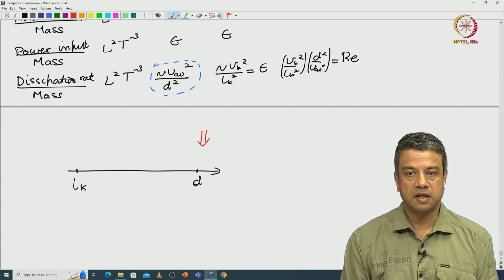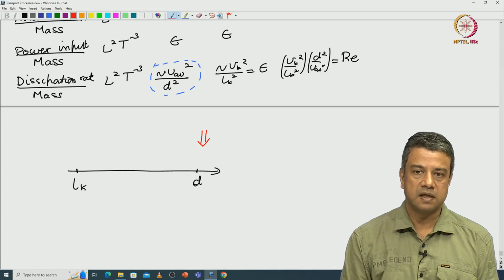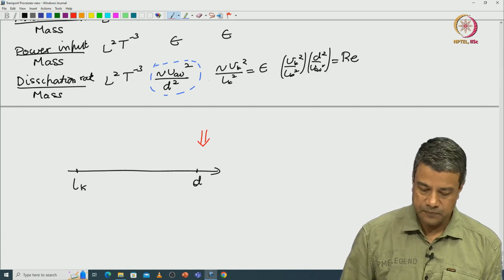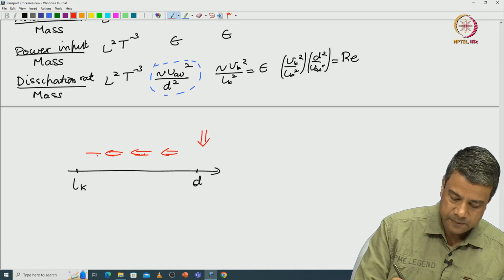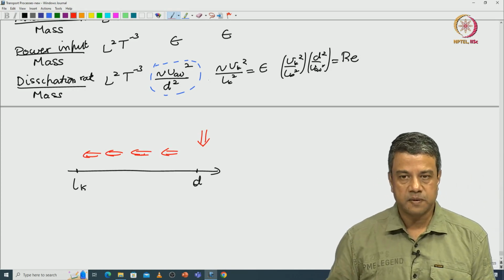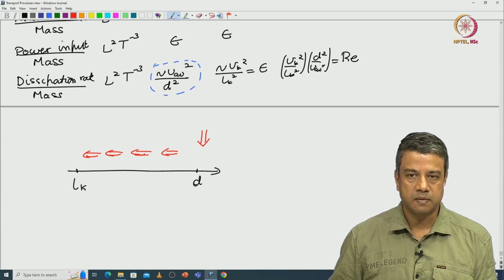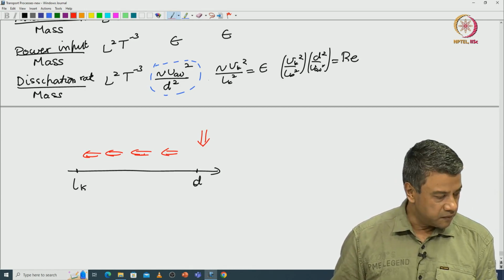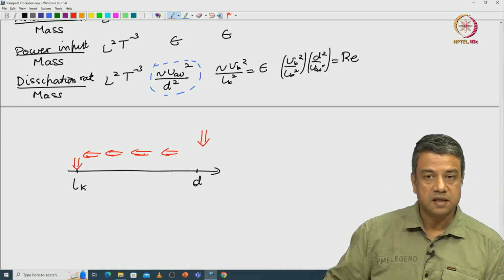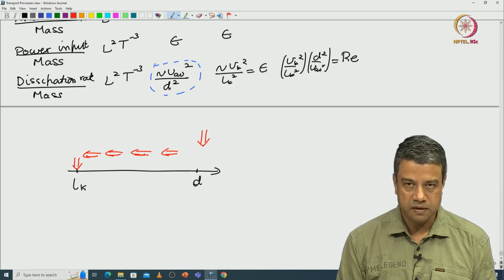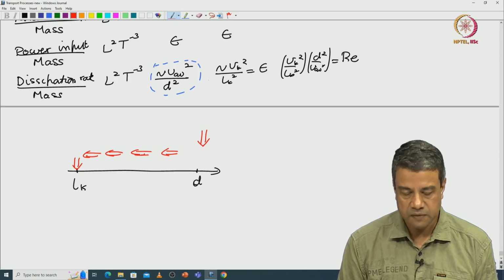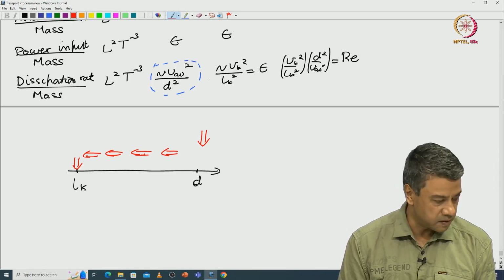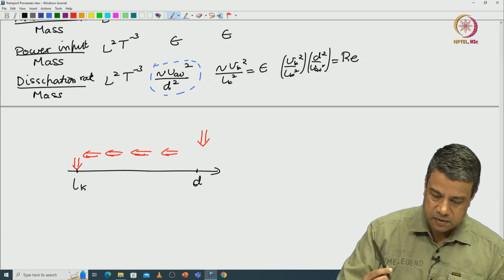That pressure difference is applied across the entire cross section. Therefore, the length scale for the energy put in is at the largest scales. That energy gets transported due to smaller and smaller scale eddies. At the large scales, the rate of dissipation of energy is much smaller than the rate of energy input, because the Reynolds number is much larger than 1. The flow itself creates smaller and smaller scales, such that at the smallest scale, the Kolmogorov scale, the Reynolds number is order 1. The rate of energy dissipation is comparable to what is put in at the large scale, and therefore, you have energy dissipated at these smaller scales. This is what is called the turbulence cascade.